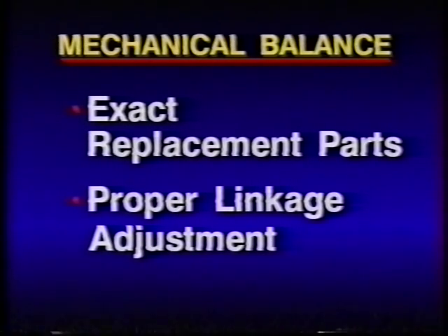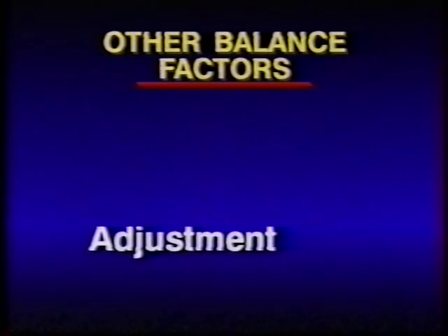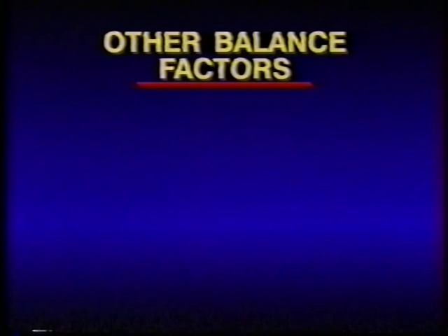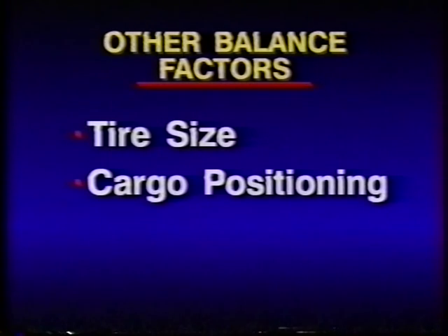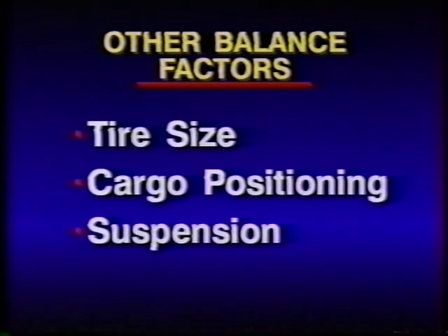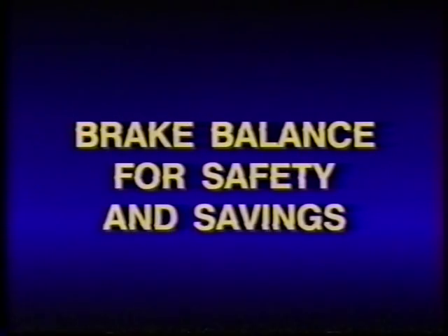Other factors that must be considered in achieving overall brake system balance include tire size, cargo positioning, and the effect the suspension may have on load distribution. Brake balance is not always easily achieved, but the effort can pay off big in safety and savings.